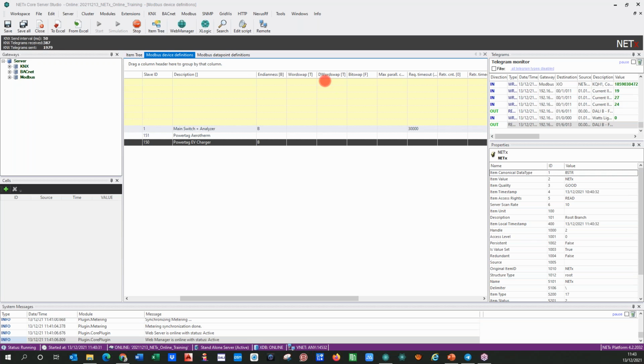This is also typical because some of the registers, and it's very frequent, need 32 bits to code the values, for example to have a bigger resolution or a bigger range. So you need double registers with 4 bytes. So the double word swap is the same, to swap the position of the bytes because the information is positioned in the bytes with highest weight, we can say. And this is true by default.